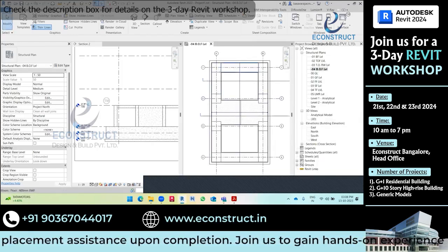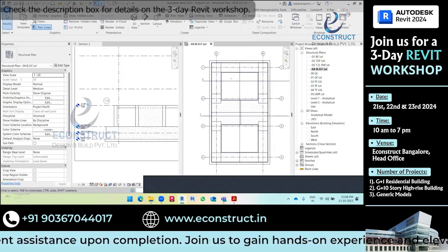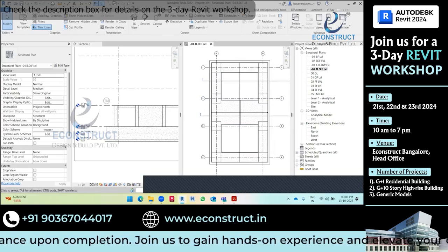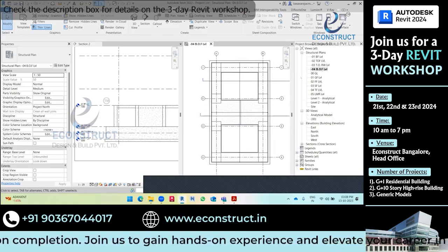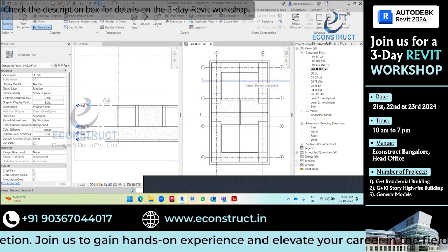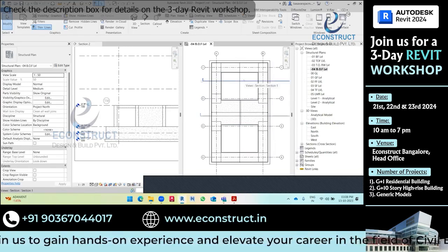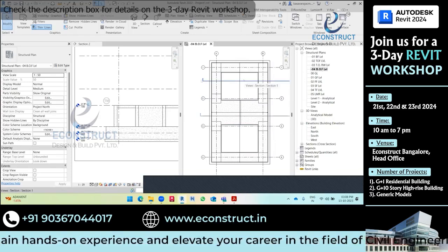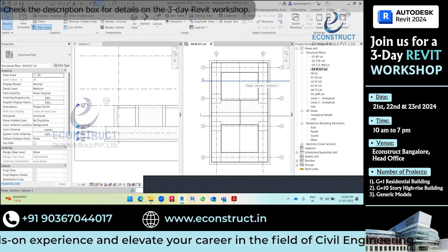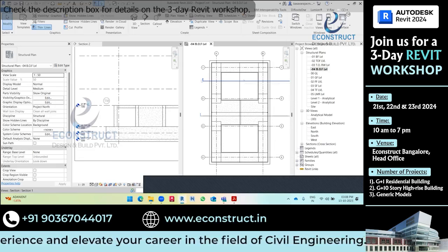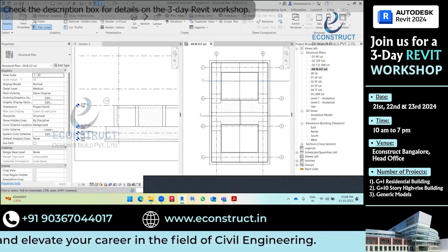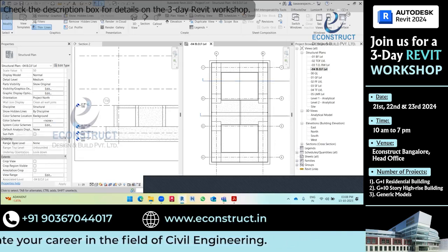Okay, here, for example, now we are in the bottom of the footing. If you want to see just the reference lines of the top of the footing or basement floor level or any other level in this view, in the properties panel, the underlay option is there.